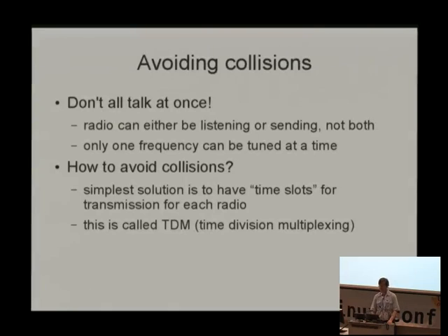Okay, so what about making this thing useful in a real world environment? You can't all talk at once on the radio. Only one person can transmit on a particular frequency. It doesn't have a separate receiver and transmitter on different frequencies. The chip just can't do that. So you're only on one frequency at a time. So only one person can be transmitting at a time if you want the data to get through. So you've got to avoid collisions, avoid talking at the same time.